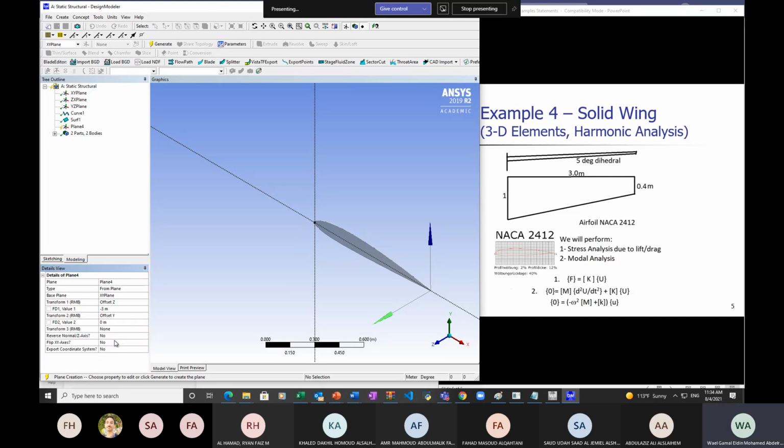So I have an offset in the y direction, offset y of 0.2625. I'm sorry. What are these numbers? What are these three numbers? You see this point relative to this point is 3 and 0.25 to simulate the 5 degrees and the 3 meters in here. Okay. Are you following? Can you perform this on your machine? Minus 3 meter because I want to draw it to the right, opposite to the z. Of course, you can put it 3, but you will be drawing the other half of the wing, the left half, which is just fine.